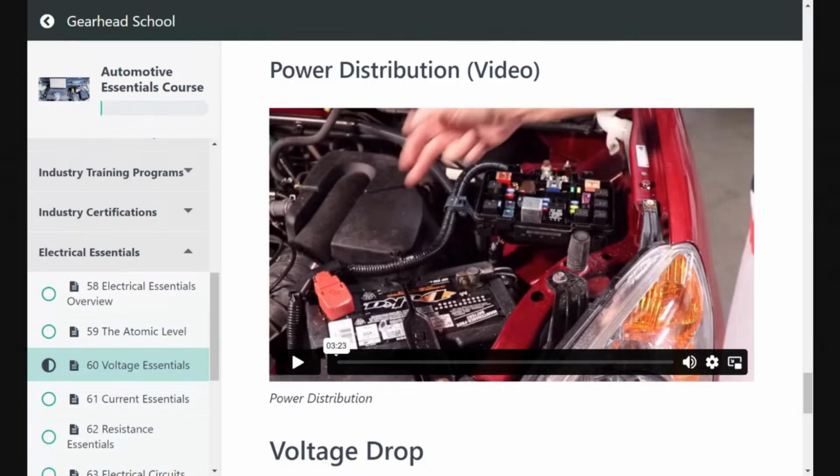It's not protected. So if engineers have any sense at all, the fuse box will be very close. That's why I made a video and showed this. This fuse box is literally within inches of the battery. So the cable from the positive post of the battery to the fuse box, a big heavy cable, is not protected against a high current. If something wears through that wire and it gets to ground, hopefully it'll burn the cable in two before it gets so hot the battery could explode or melt down.